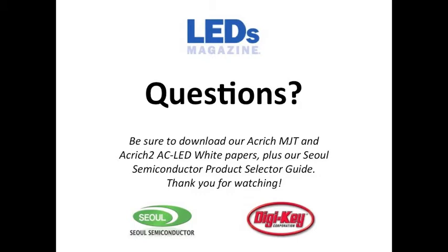But as far as reliability, electrolytic capacitors last 10 to 15,000 hours. I mean, you can overspec them. You can, but you're typically going to pay for them. They're going to be larger, and that's going to create a larger package size. As far as the frequency, we're operating at 120 hertz currently. So basically, we're doubling the 60 hertz waveform that's coming in North America.